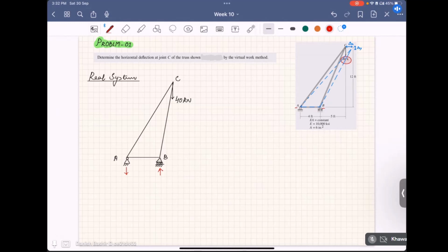So because of this, we will try to deduce the member forces in each structure. For example, first I will show you one small calculation, then you will do all the other calculations. For example, this is AY here, this is BY here. So if we take the summation of the moments at B to be equal to 0, then we will write.